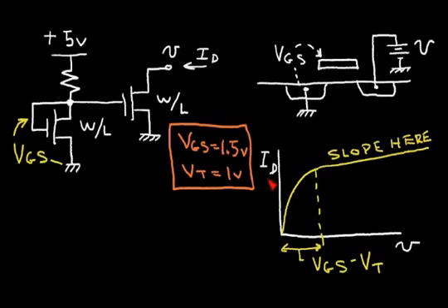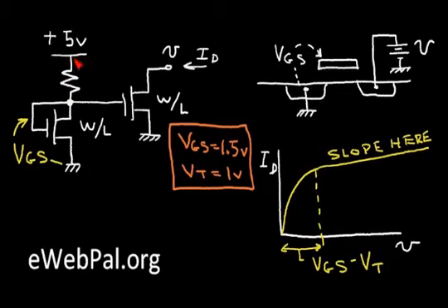At the left, I have two N-channel MOSFET transistors. The transistor at the left has the gate connected over to the drain, and the drain connects to a resistor up to plus 5 volts. And this resistor sets the current in the transistor at the left.